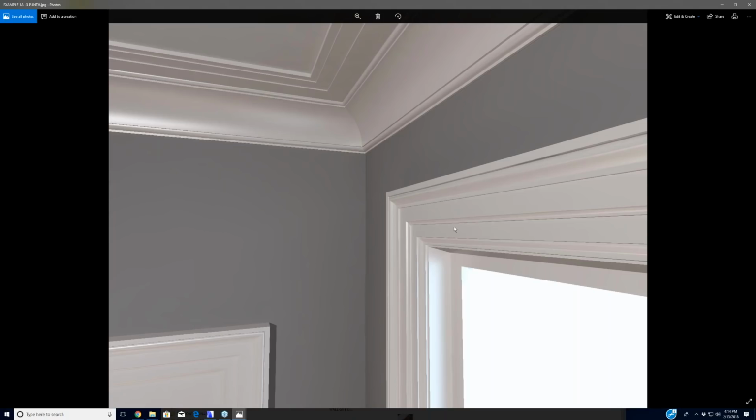If it's a local lumberyard that's going to run that profile, that is now a 2D file. You take that 2D file, place it on a scratch pad or a worksheet or on your floor plan, and then click inside that little profile and create a morph. And then that morph is mitered flat on plan to give you this look. Same with this cornice, and I'll show you in floor plan what that looks like.